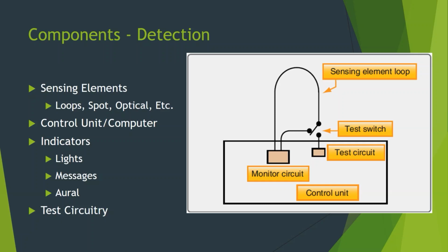That's okay, it can still give an indication. But say the loop was disconnected here and here. Now what happens if you get a ground or an indication up here? Did you get any kind of an indication? Nope. So one of the tests would be, it makes sure that there's continuity end to end, to make sure you don't have two potential breaks somewhere in that loop that would cause there to be a non-sensing portion of it.